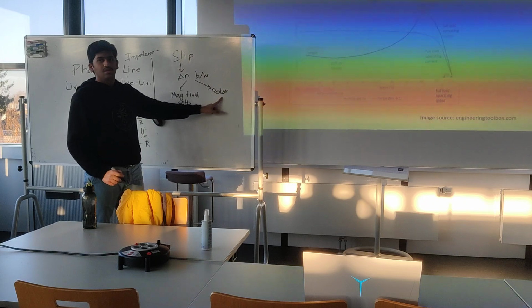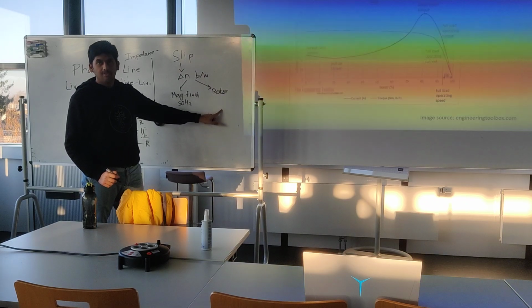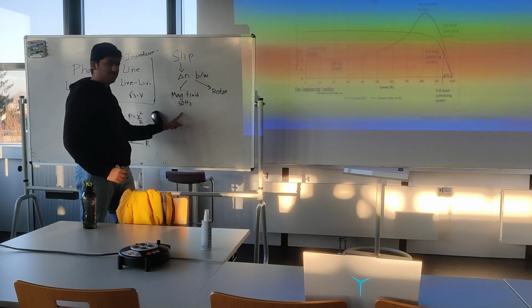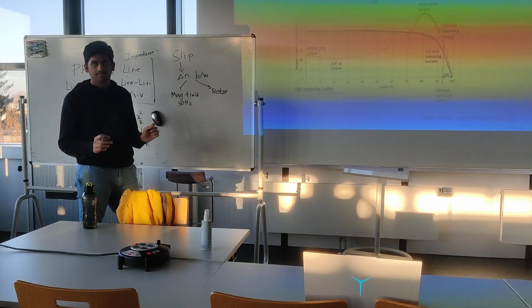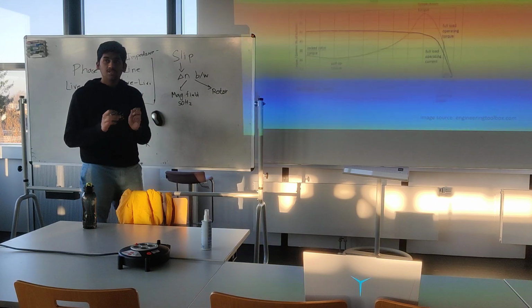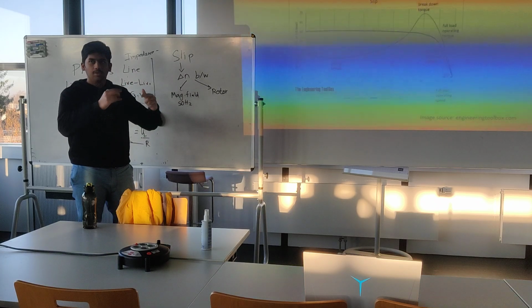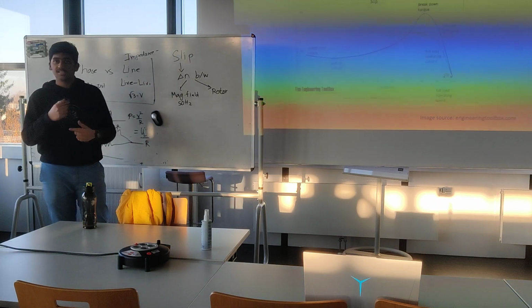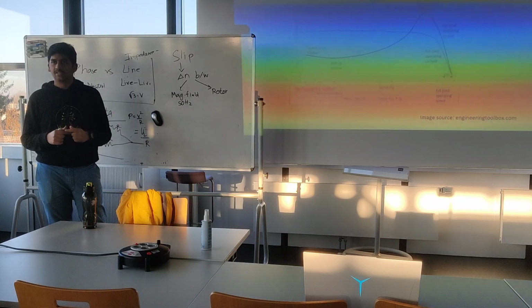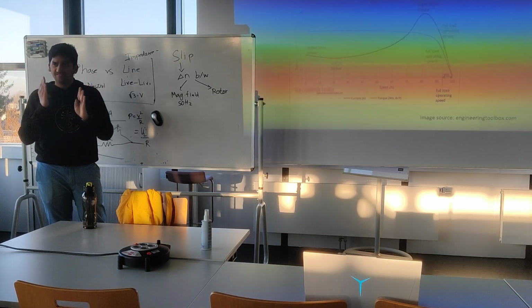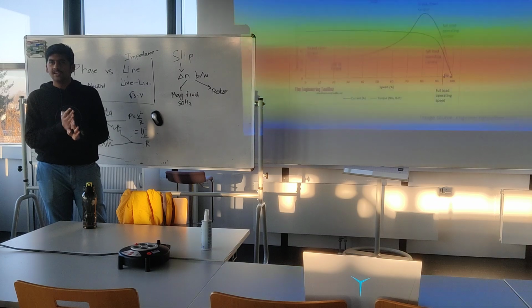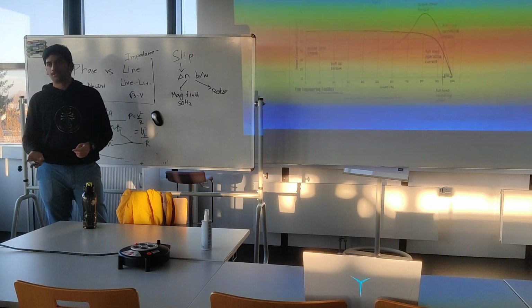If the rotor rotates at 3000 RPM, it's going to match this 50 Hz, and there is zero slip. And at zero slip, there is no magnetic field difference between the field induced inside the rotor and the field made by the stator. They are perfectly in sync. And when this happens, there is zero force, meaning zero torque.